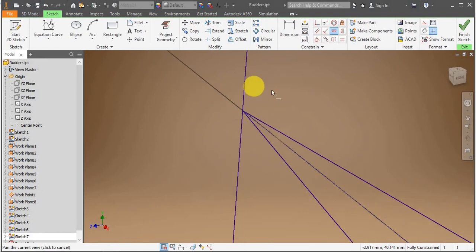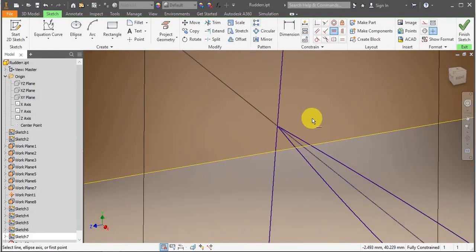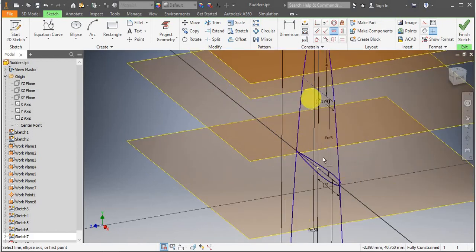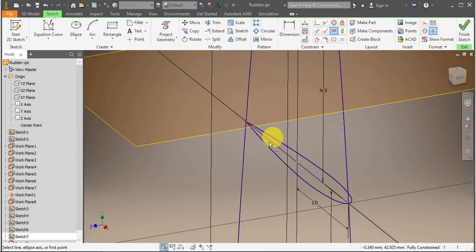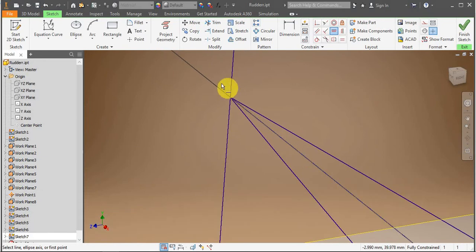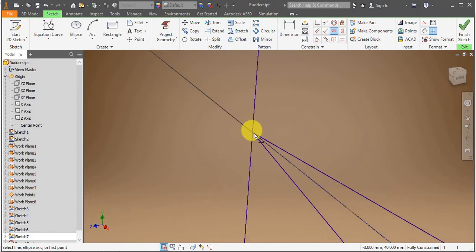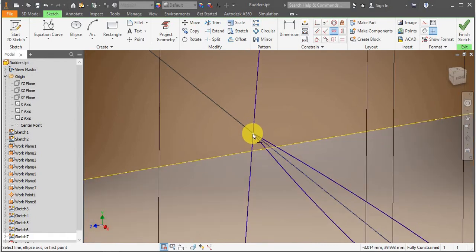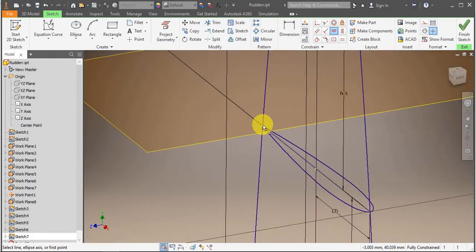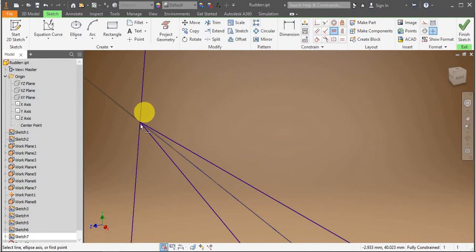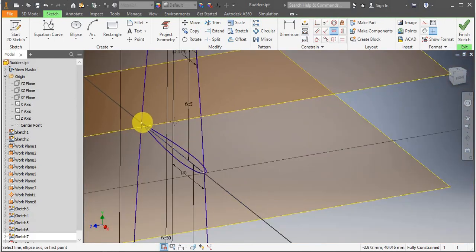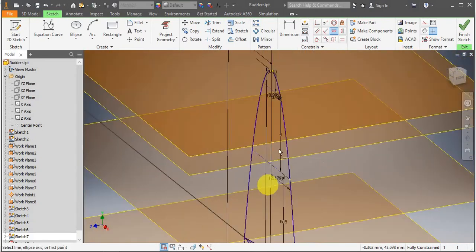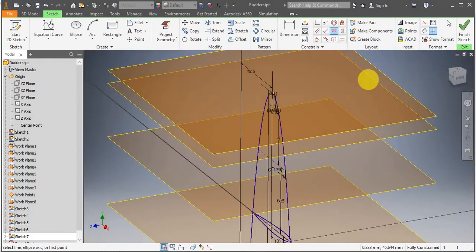Just a little detail. Normally, if you were intending to build up this foil, you will probably use a little radius at the leading edge rather than having that sharp corner in there. However, if we try to do the same task with a radius, it would just complicate things unnecessarily. But it's just a note, it's something to bear in mind.